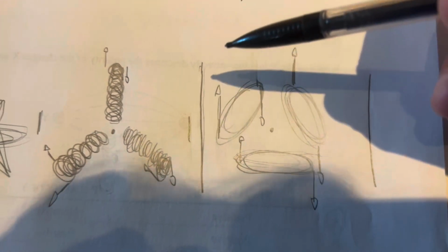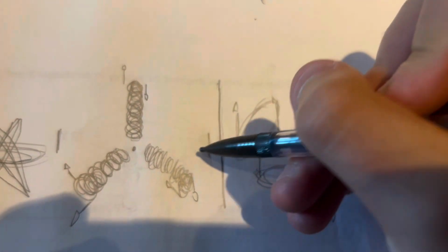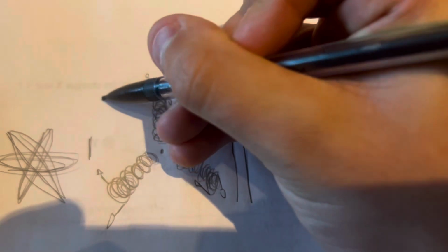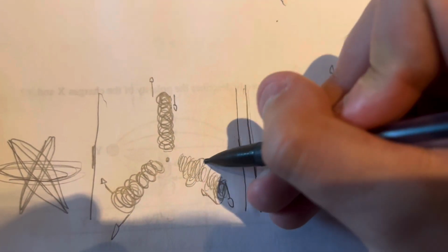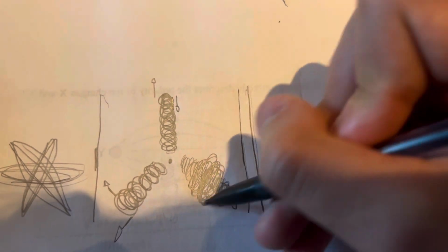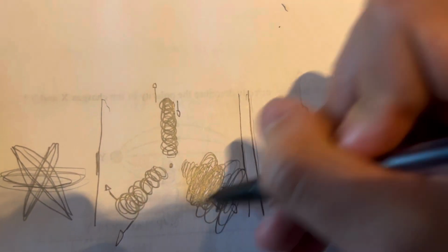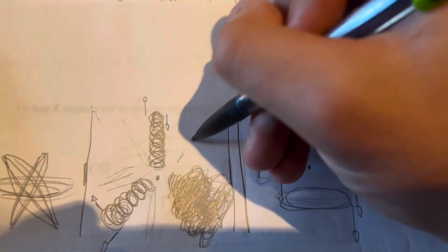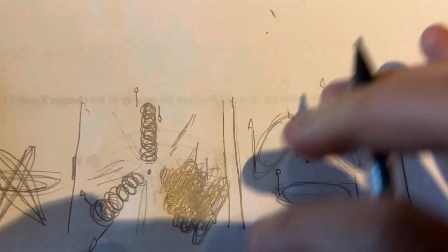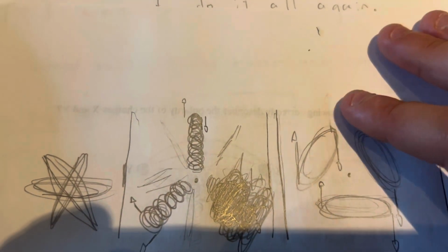And if you really want to maximize this, you actually want to mix these two designs together. That means, let's say the magnet was this big, you could barely rotate in there. You would actually want to just wrap more and more and more, so that you get this triangle shape, right? And if you had 3 of them that ended up with these triangles, you'd be using all of your space, and you would have as many loops as possible in that space. Now, that's one way to maximize it.